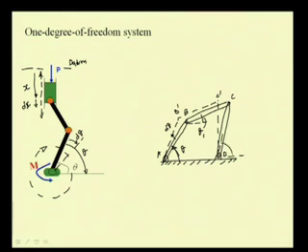the angle of this link theta 2, we can write these angles theta 1, theta 2 in terms of this angle theta, and so any displacement d theta will result in the displacements d theta 1 and d theta 2, which is again possible to write, because these link lengths are constant. So, these 2 angles can be determined in terms of this angle theta. So, again this is a single degree of freedom system.